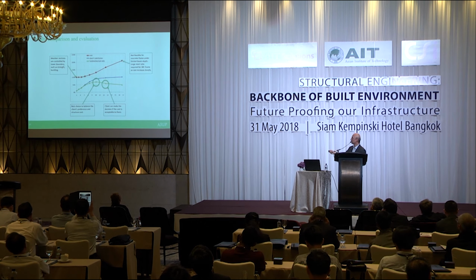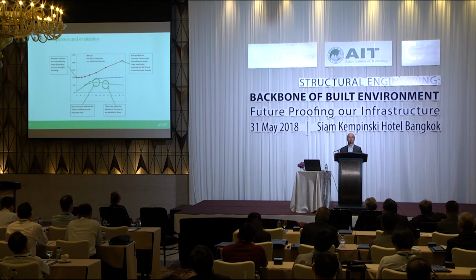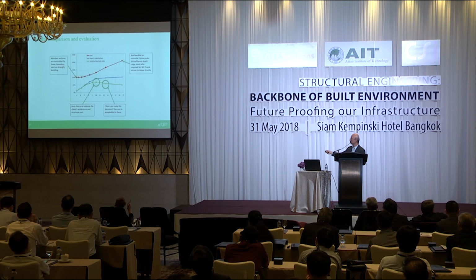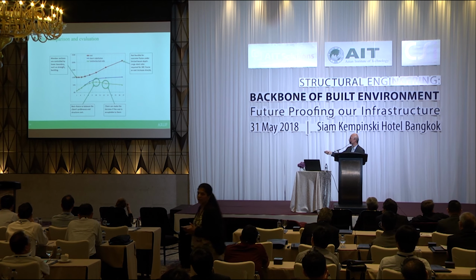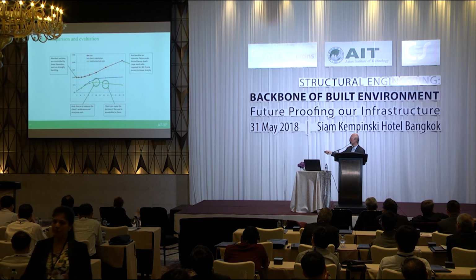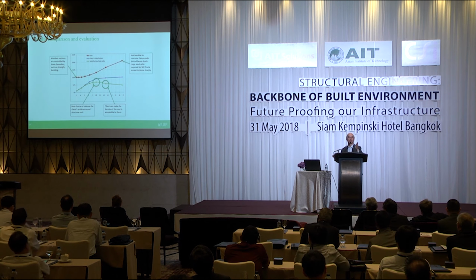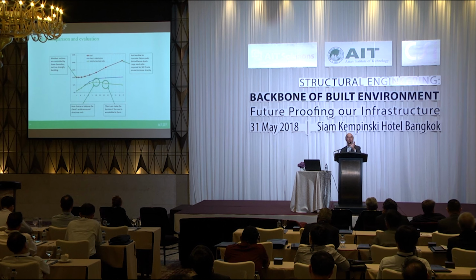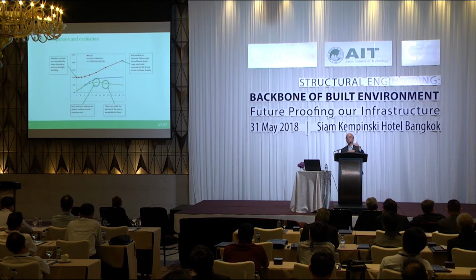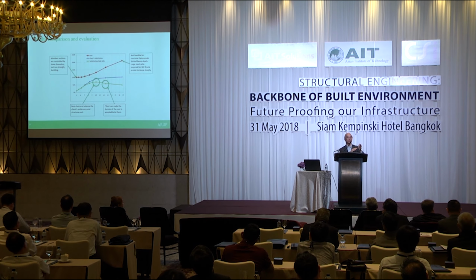Now, within this, we can also work with the architect and the client, say, okay, this is 100% cost, and this is the number of columns or the spacing and so forth and so on. Then here you can see that you can have a choice of like 9 meter or 10 meter or 11 meter or 12 meter grid that will give you the most optimum balance between what the architect or the client is looking for in terms of spacing, and also in terms of beam depth and structural cost, okay?